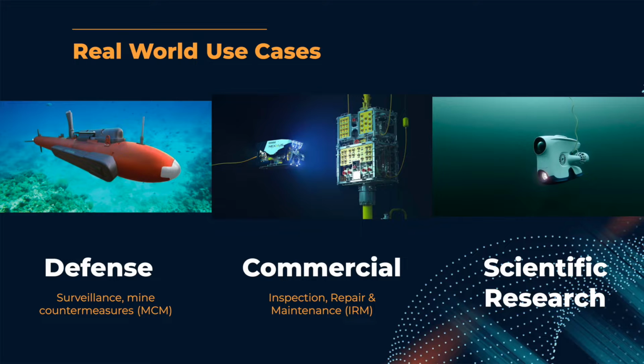But if you look at the real-world scenario again, that's limiting in a way, and it's not because of the lack of wireless communication systems underwater that nobody uses it. It's just that the niche is slightly different from what we are accustomed to on land. On land, we have long-range, high-bandwidth systems. But underwater, usually you have high-bandwidth systems which are very short range, optical or RF. Because electromagnetic waves get absorbed rapidly in water, when you go long range, you use acoustics, which means it's very, very low on bandwidth. So you have to make your vehicles work with either these very short-range systems or very low-bandwidth systems.